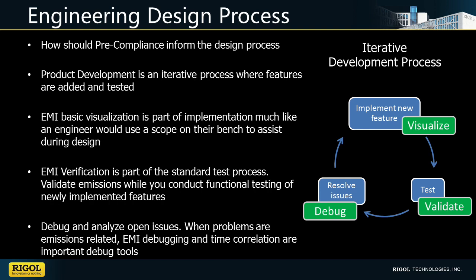As you move into a test phase, you can use EMI validation tests with a little more setup to help you make sure that emissions, whether they're radiated or conducted or immunity, aren't causing issues for you as you integrate your new features with your existing system.